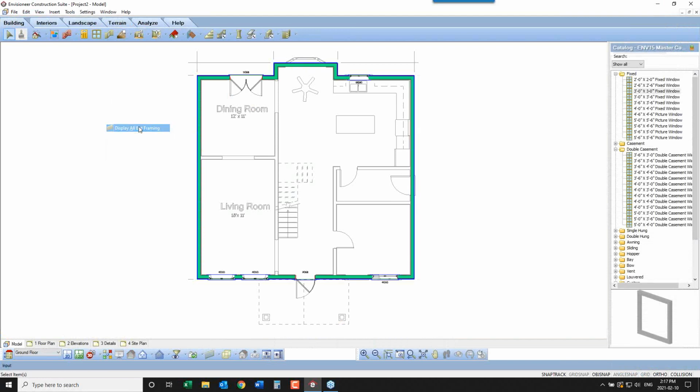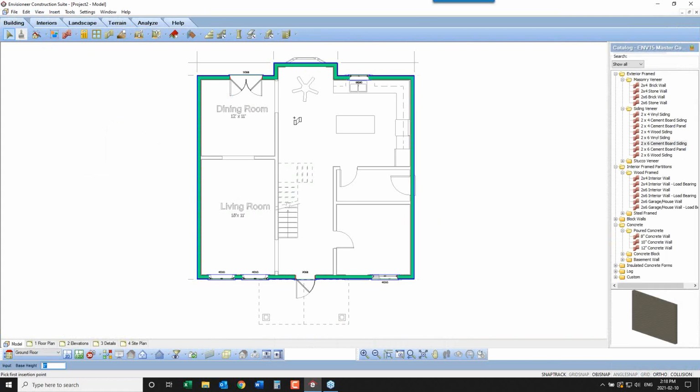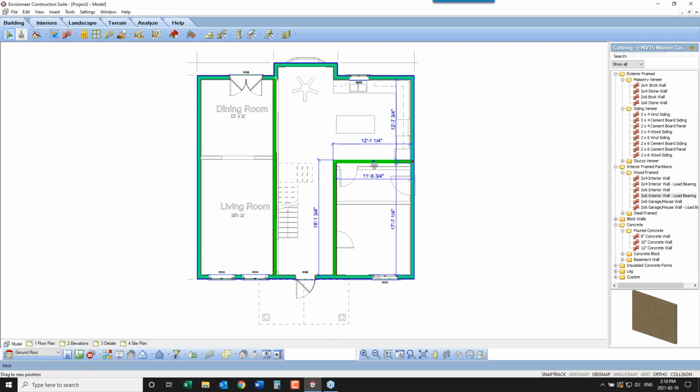I'm going to get this out of that mode again. I'm going to add in a couple of more walls here to divide up our plan. I'll grab some interior walls. I've got a 2x6 load-bearing wall that'll start here and end off down here, and one that'll come up here and come up to our planned height here, and just clicking in there, it wants to put it there, and I'll just move that back in, seeing another corner, and I'll grab a 2x4 wall.